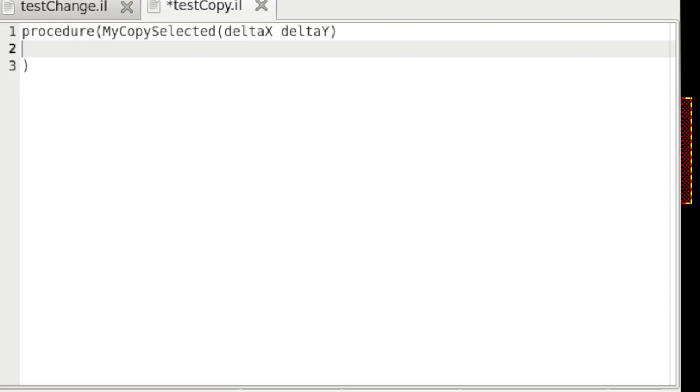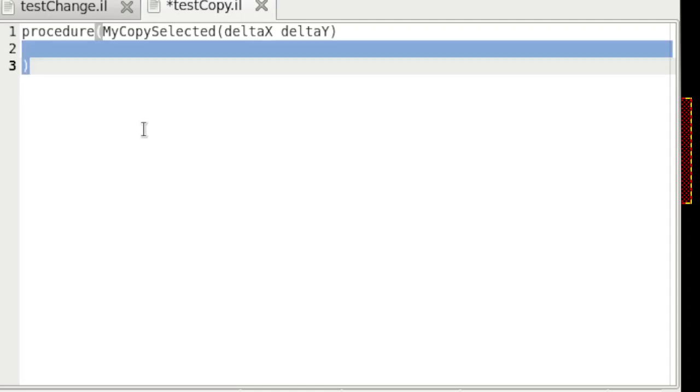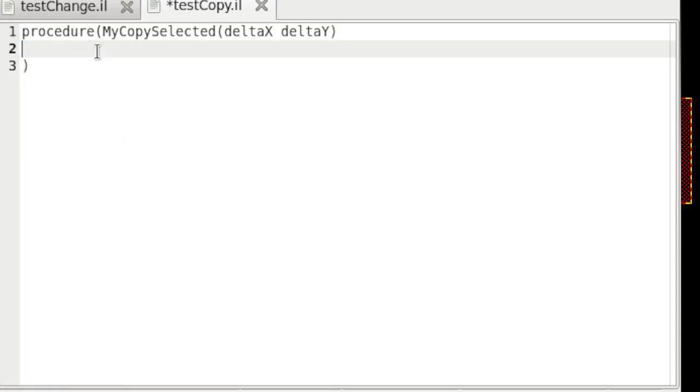So what do we want to do? First of all, we are actually doing the copy operation, right? So for that we need a command for copy. There is a command in Virtuoso, that is your db copy fig, right? This command actually copies anything whichever you select, but it needs three options.